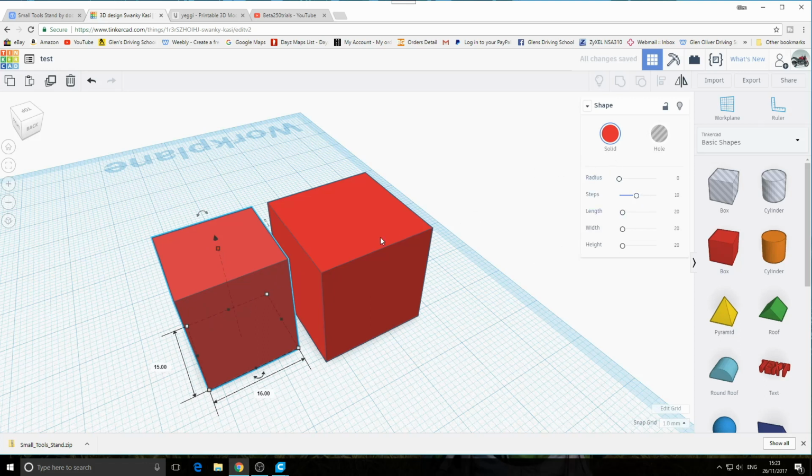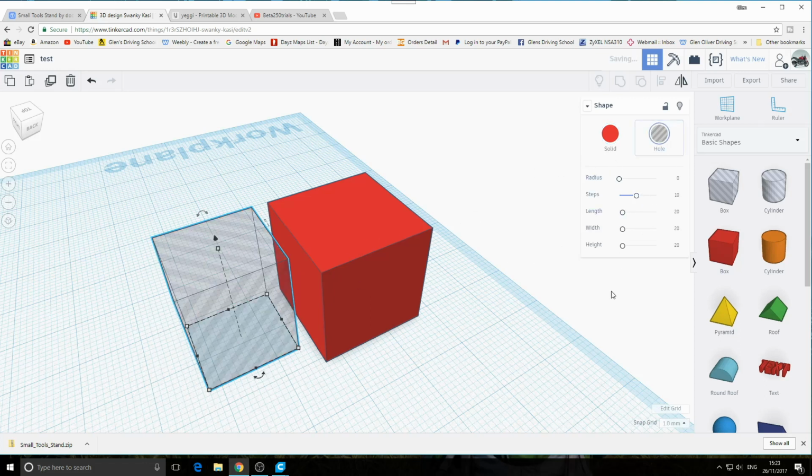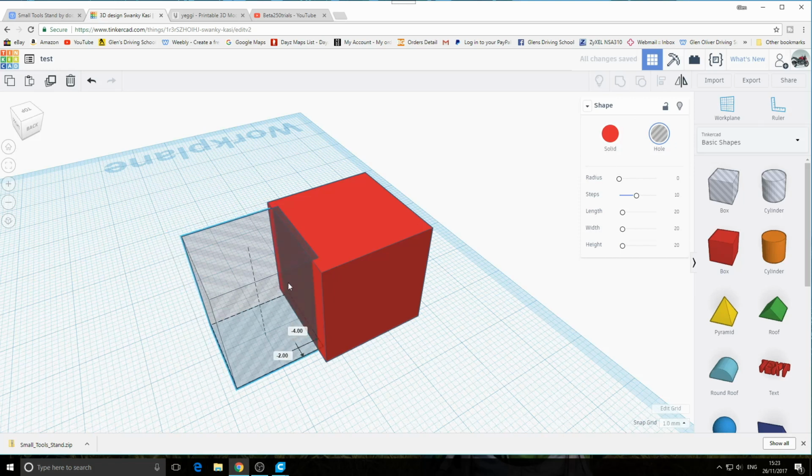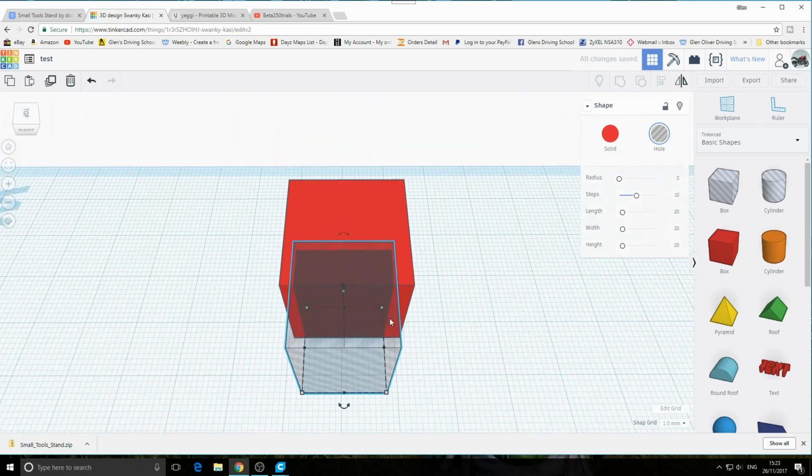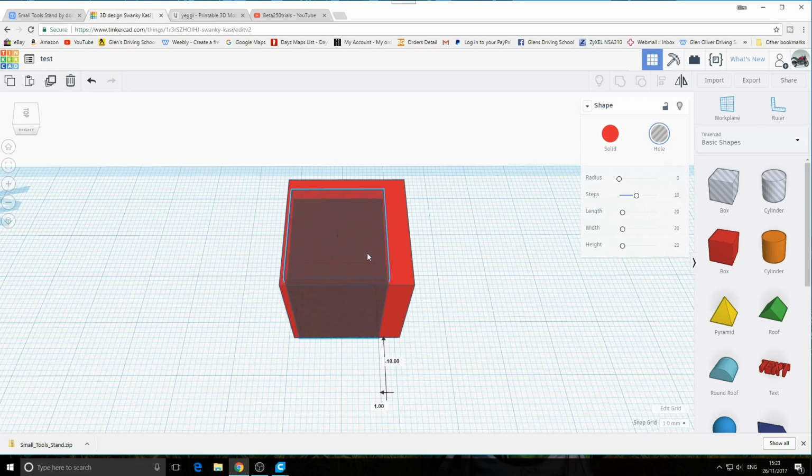I can make this one into a hole and slide this one into there. Now what it does, it cuts in. It's a bit bigger. Yeah. So if I wanted to make something like that, see how it locks to the 1 degree increments. If you come down to the bottom, you've got 1 degree or 0.1's the finest, and then it gives you that fine control.